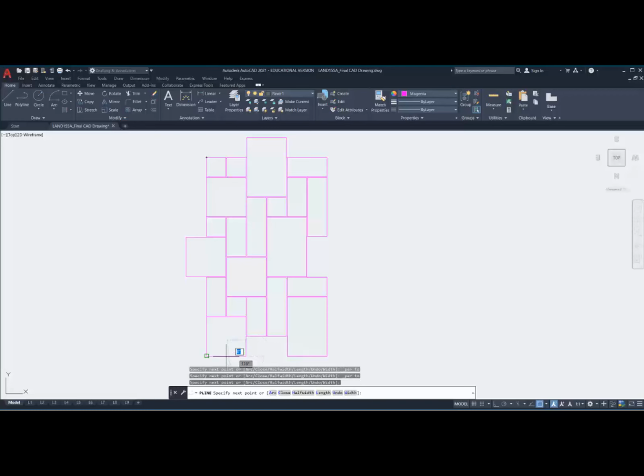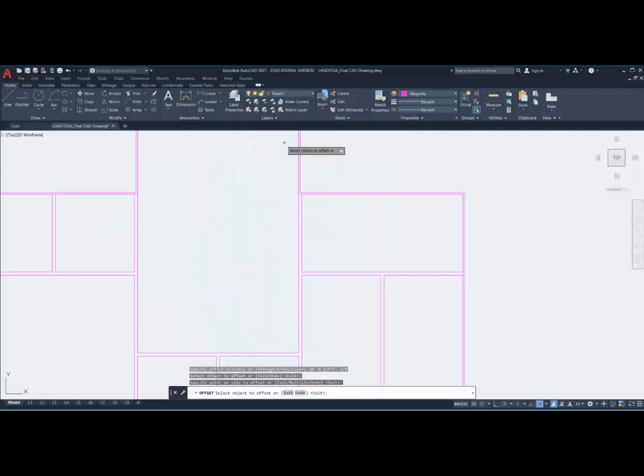Now, in some cases, we want to make sure that a corner is lined up with a corner. On curved driveways, it's not as critical because obviously the curves will cut into any of these square pieces. But if we've got a nice straight section, we want to make sure that we don't have what's called slivers. And so when we make the width of the driveway, we make it based on the modular distances of this particular grid line that I just drew, or I'm going to offset here by 0.25, because that allows for grout on the edge of each tile from one end to the other.